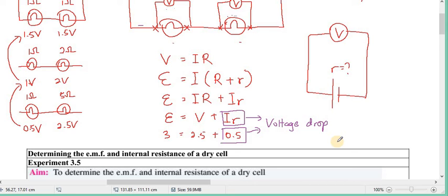So the 240 volt maybe will drop, let's say left 200 volt only. 40 volt taken by the wire. That means the voltage drop is 40 volt. So the fan that you connect with a wire straight from here to block D cannot function, because it doesn't get the minimum 220 volt.